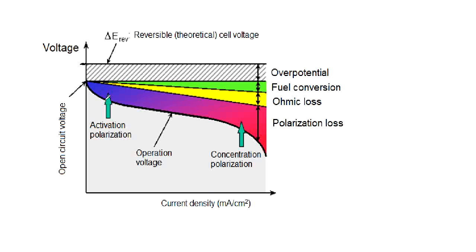Then, once you start drawing some current out of the fuel cell, there are other losses. Very quickly, the voltage drops because of activation polarization. Then, as you increase the current density, the fuel conversion factor might decrease because there is higher possibility of the fuel crossing over to the products, and also due to the higher current there will be higher ohmic losses. Typically the operation of the fuel cell is some trade-off between the current density, so that the fuel cell has a given size, and the cell voltage not being too low, so let's say it would be somewhere here.